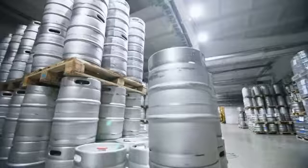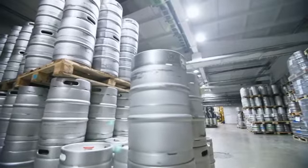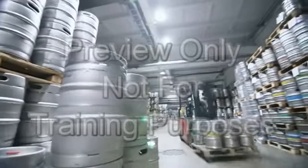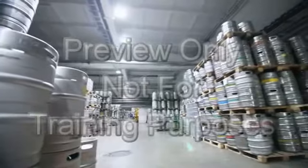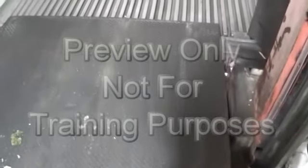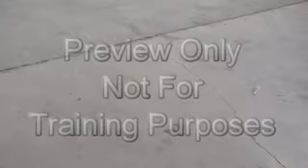Workplace conditions. Operating a forklift safely also requires awareness of the workplace and the conditions under which you are driving. You must be aware of things such as physical conditions, pedestrian traffic, and loading docks, just to name a few items. All operating surfaces must be strong enough to support the forklift, the operator, and the load.